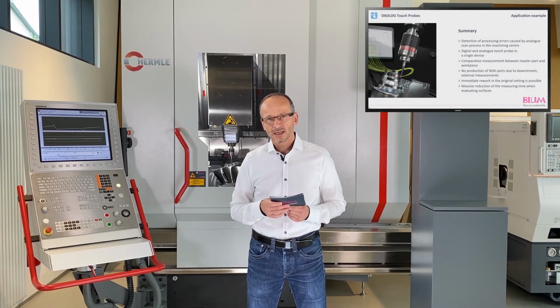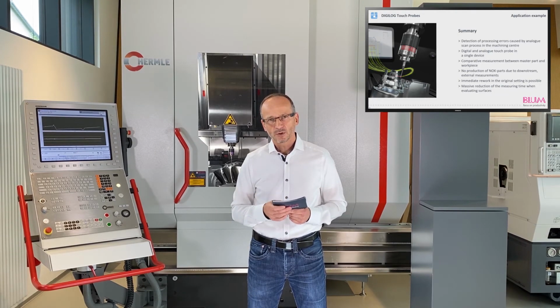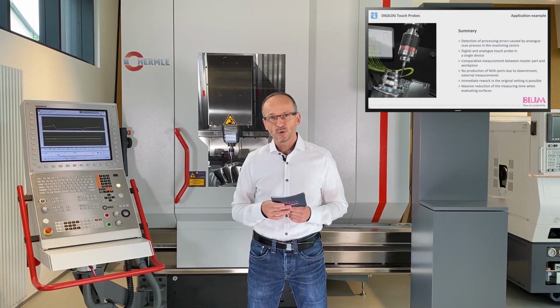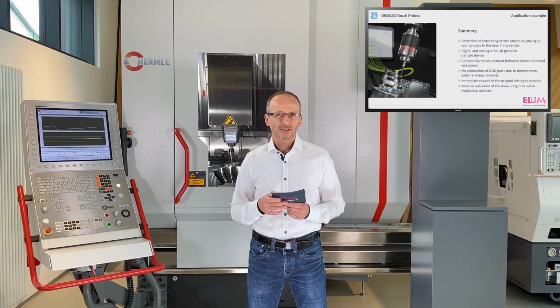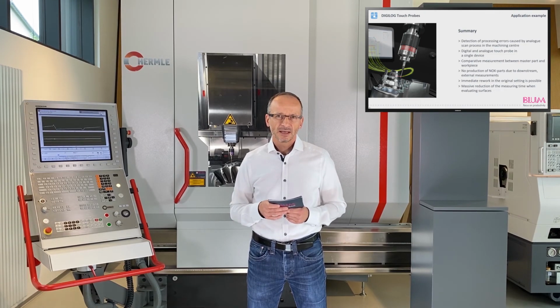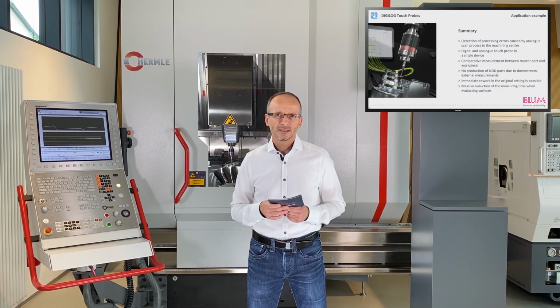We're almost at the end of my talk. There are still numerous application examples I could tell you about. So let's summarize. DIGILOG is the combination of digital measurement technology and analog measurement technology. With an analog measurement, we don't just record a single signal but a data stream with thousands and thousands of measured values. This type of measurement allows the scanning of surfaces, and not just simple profiles, but also very complex ones. We compare the actual profile with the target profile and recognize whether the component is within the predefined warning and tolerance limits. All this leads to the following advantages.